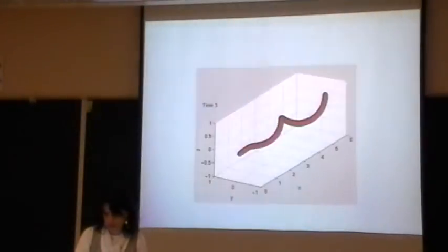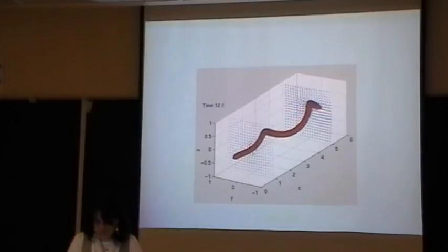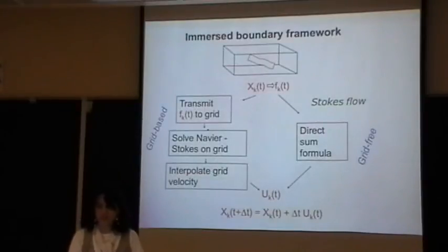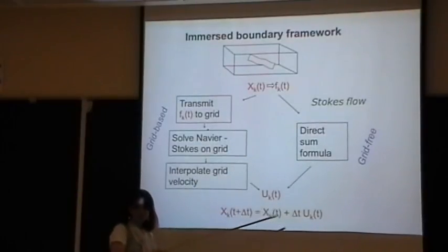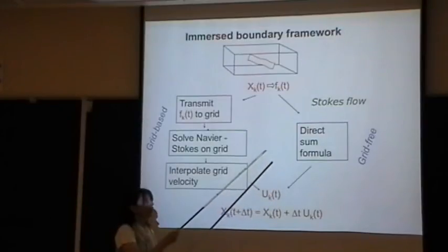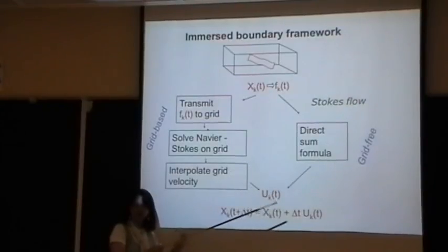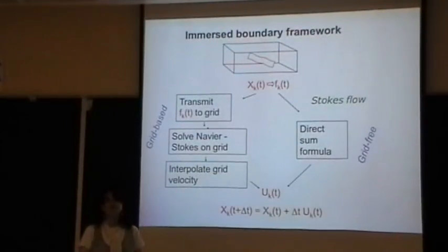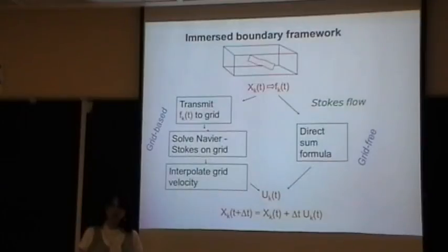So here are just some amazing simulations now. Just some pictures using this framework. I should say, what I'm going to talk about tomorrow is this transition here, where suppose that we don't have the Navier-Stokes equations, where the Reynolds numbers look small enough that we could make the Stokes flow assumption. There the equations are linear. You have a delta function forcing the Stokes equations. You will get the classical Stokeslet solution, which I will derive for you. Numerically, the Stokeslet solution is not so great because it's singular where you apply a force.